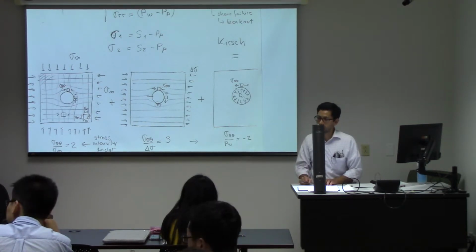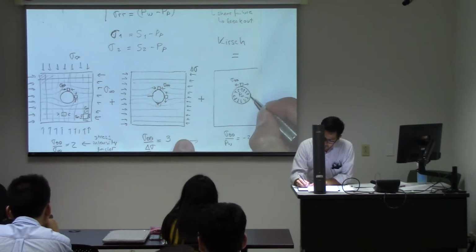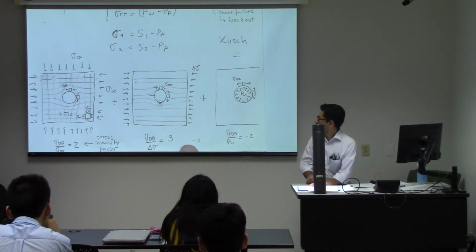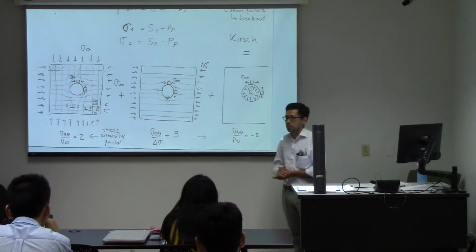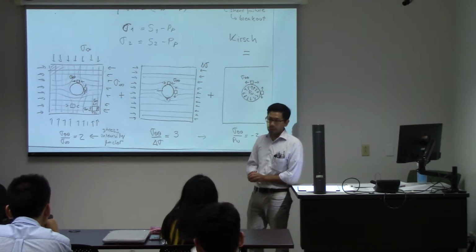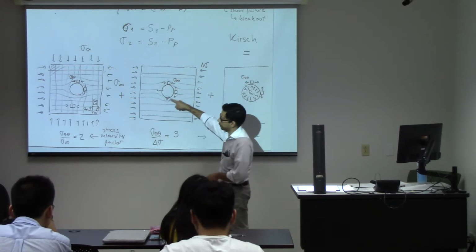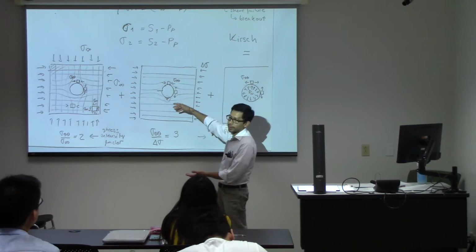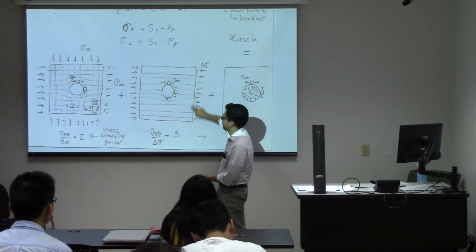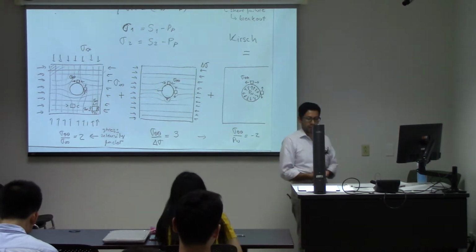Yes? A little conceptual question. The stress intensity factors 2, 3, and -2, are those exact? Yes, those are exact, under the condition that the cavity is significantly smaller than the domain. I'm drawing a rectangle around the cavity just to make it a little bit clearer, but I'm assuming this is in the far field. It's quite far away from the cavity.